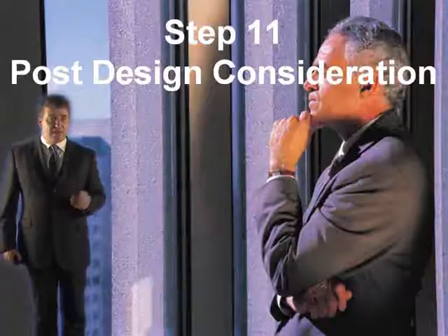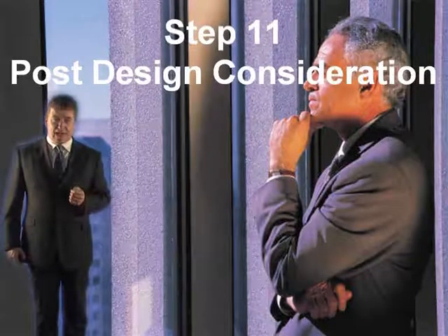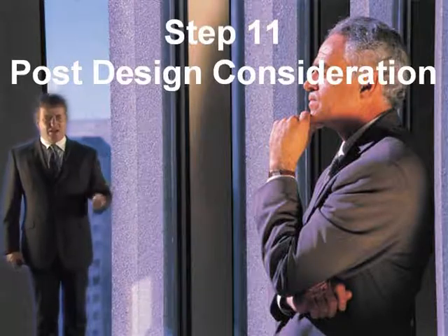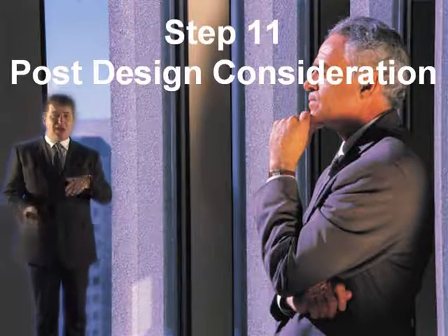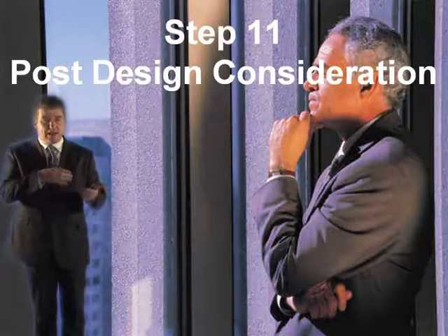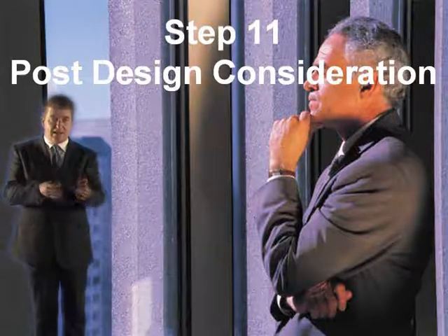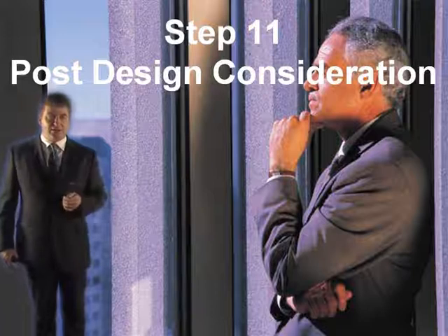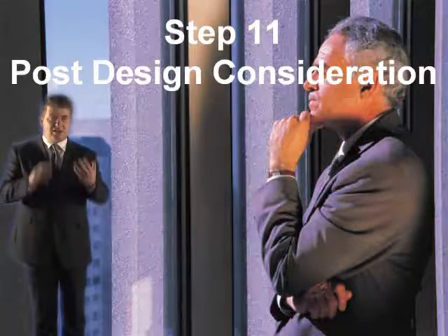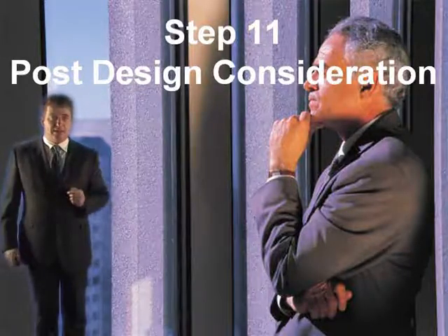The final step, move on to step 11, which is the post-design considerations. In this case, you've got to consider weather conditions. Again, tall buildings may have an impact on it. And there's no smoke curtains in this particular case. If there are, you've got to be careful they don't deflect. In other words, carry out your post-design considerations, testing, maintenance, etc. That completes this exercise.